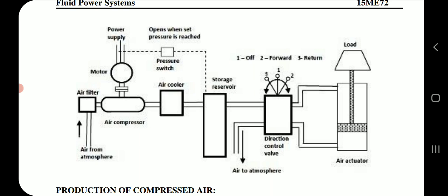Air from atmosphere to air filter to motor power supply, then to air compressor, opens when set pressure is reached, pressure switch, air cooler, storage reservoir, direction control valve, load, air actuator, air to atmosphere.